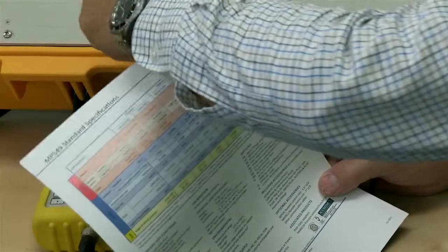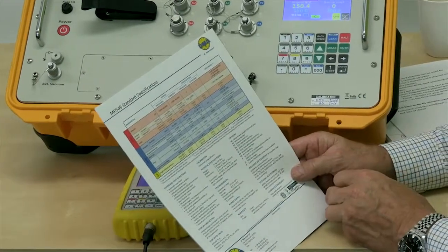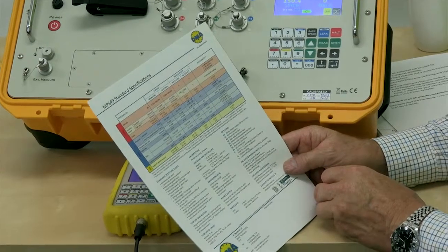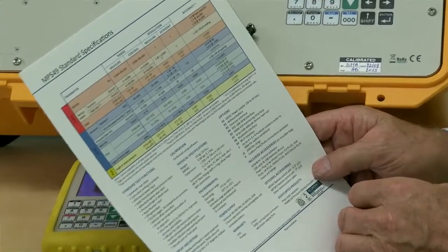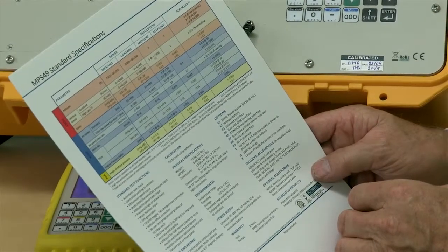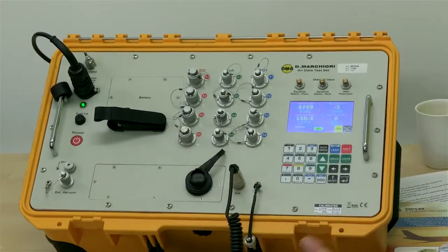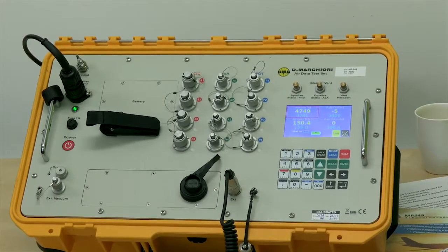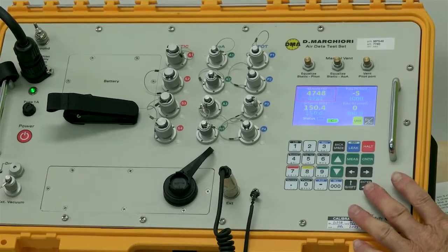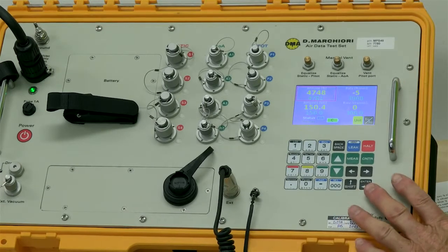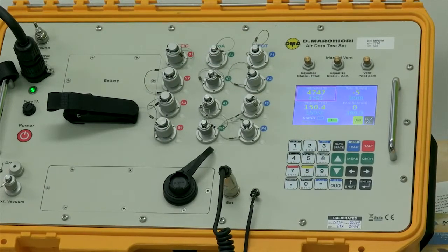This particular plate here can be removed, and you can fit into there, for example, an Ethernet interface, an IEEE 488 GPIB interface. You can have an ARINC 429 interface. We can have a grey code device readout. We can have Bluetooth if you wish, and a Wi-Fi interface. All of those are capable if that is removed. Those particular interfaces tend to mean that this is no longer a flight line unit. You're going to be using it in a laboratory or workshop environment, because you've then just removed the beauty of the weatherproofing that the standard box gives you.